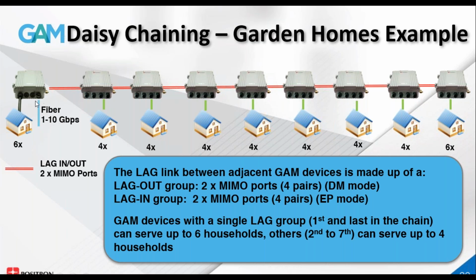And you'll notice that the rightmost one has a fiber or SFP plug. The other ones have, from the left, those are the copper pairs going to the home. Then the copper pairs for the uplink, the copper pairs for the downlink, and then the last port is used for power, so that we can power each of these devices, independent of whether they are currently serving active customers or not.